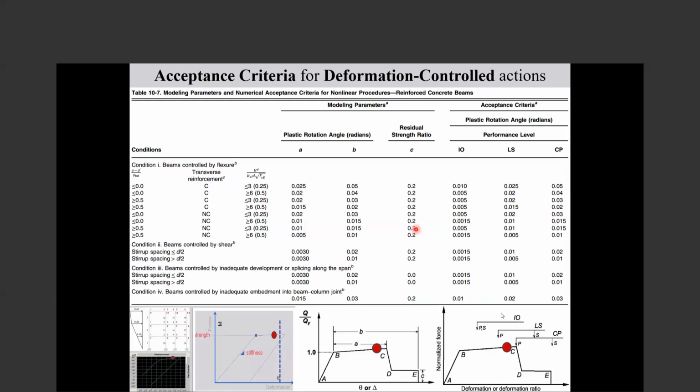So if you are using modal analysis and the mass participation ratio is not satisfied, how can we solve the problem to perform nonlinear analysis? There are 2 points. One point is methods for doing nonlinear pushover for different cases where ordinary nonlinear pushover analysis is not applicable.